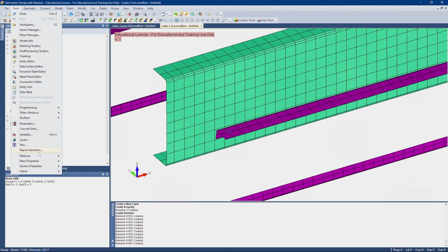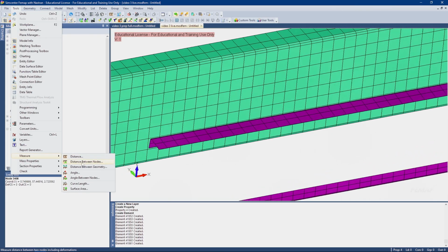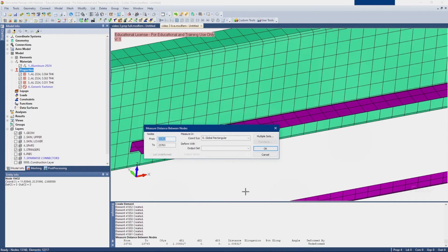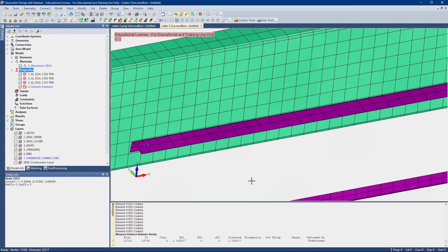So first of all, we want to start by measuring the length of our elements, the distance between nodes. We set it to 1 inch, but sometimes the program doesn't have an even increment of 1 inch between elements, which in this case I don't think it does, because I think I set this distance to 0.75 and the total wing length is 48 inches. So it's going to have about 47.25 inches to play with. It'll just default to a multiple. So yeah, you can see it's 1.005 between elements. So just copy this number.